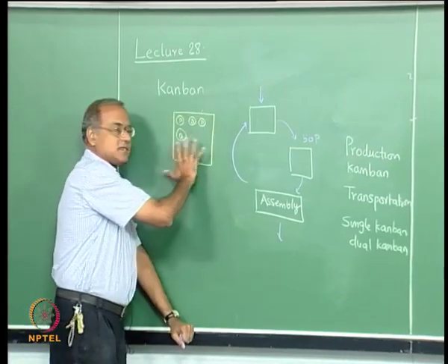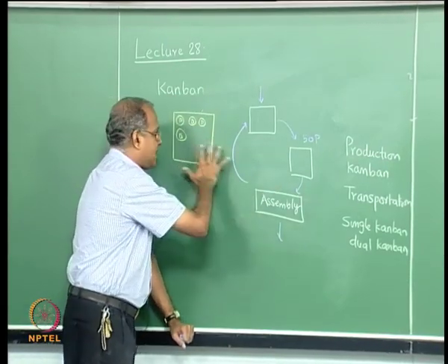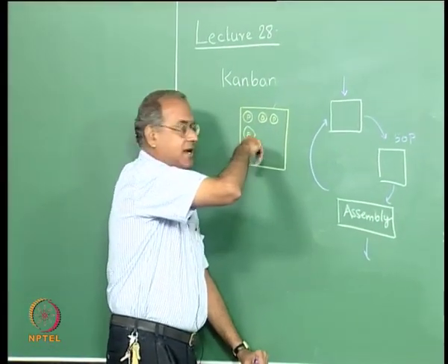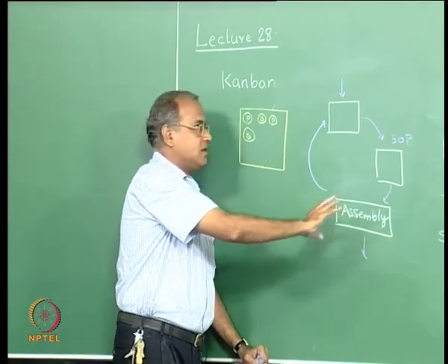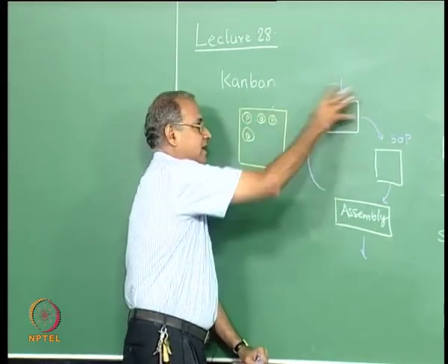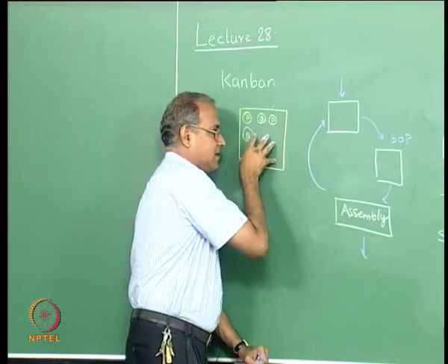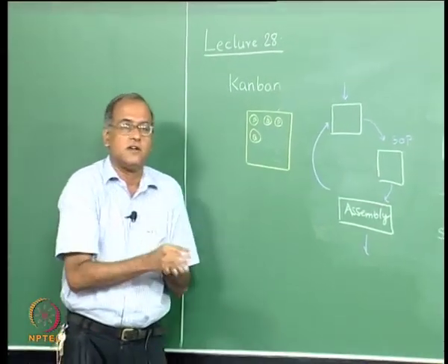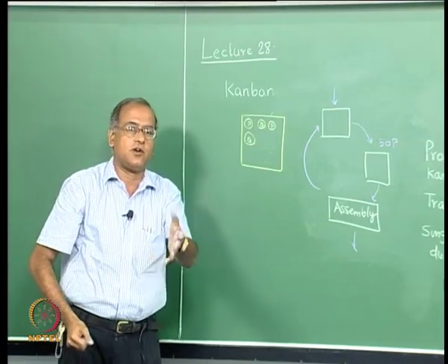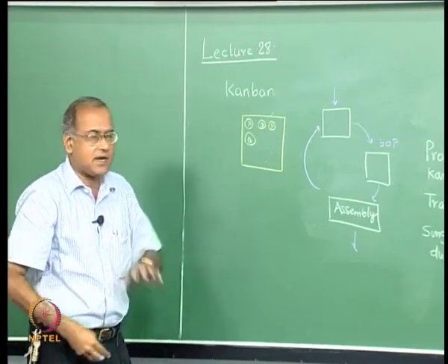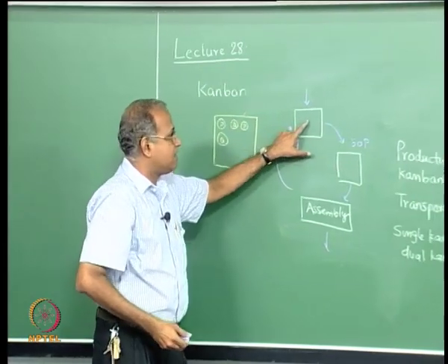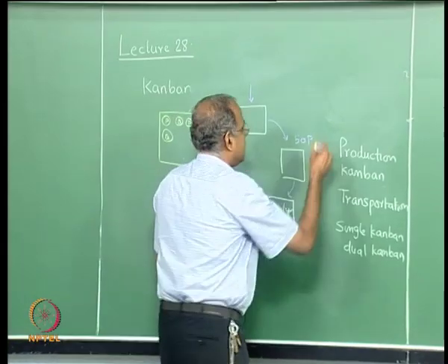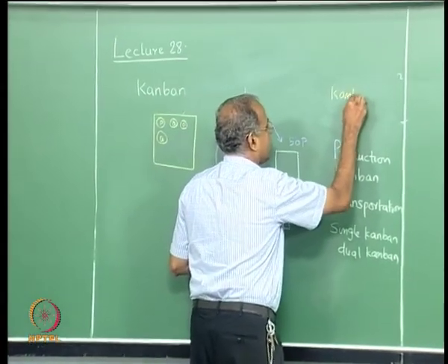This kind of a thing happens many times, but then this would involve a transporter to transport things also. So, there will be some inventory build up here, and then the inventory will also be replenished. This will feed into this and then take something, this will come put something, take it, this will put something here and take it. So, these Kanban areas would be full of containers which will have to go to different cells for manufacture. But the essential idea is to control the amount of inventory which is in this. So, the important thing here is to determine the Kanban size or the container size.